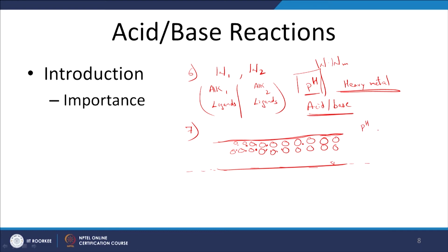What is going to happen now? In general, depending upon the kind of contaminant, there can be dissolution, depending on the pH of the water that it comes in contact with, and then that can leach again into the groundwater and contaminate the groundwater. If this is the groundwater flow direction, you are going to have a contaminated plume.